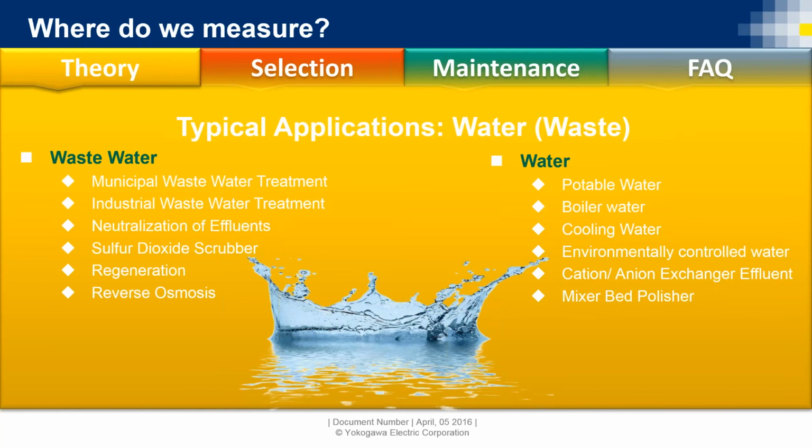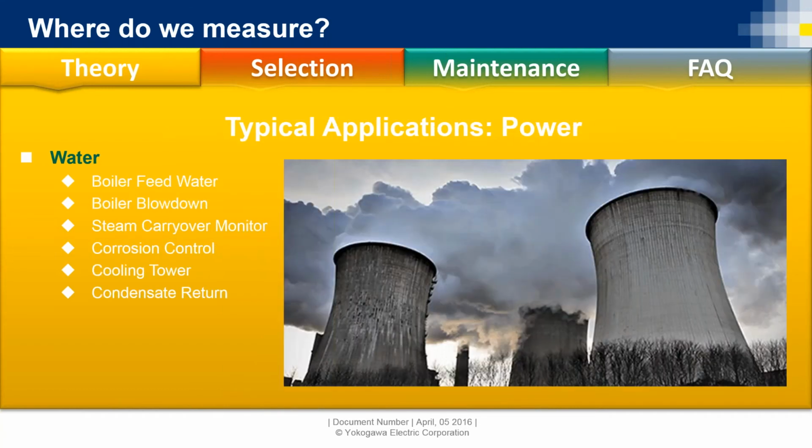You will have one pH coming off of a line, but then you're going to have what we call specific conductivity. Then that sample will run through a cation resin bed on your panel, probably. After that resin bed, you'll have what's called cation conductivity, and then that sample may go through a reboiler, and you'll have what's called degas conductivity. So you have 3 conductivity measurements for the most part to your 1 pH. So you have more, you just don't have to maintain them as frequently.